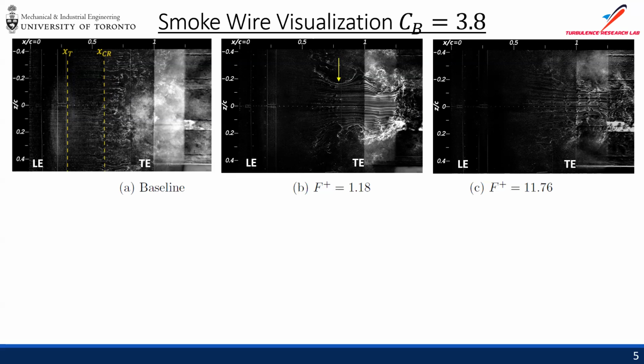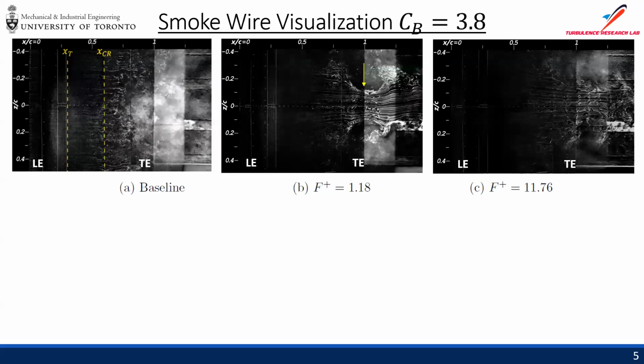So the frame we're looking at is focused on the actuated case. If you move further away or closer to the sidewalls of the wind tunnel, the span of the airfoil is not actuated, and the non-actuated zone is still separated, and it causes this contraction that invades into our actuated zone. The yellow arrow points at the contraction, and you can track them as they convect downstream if you have a series of instantaneous results.